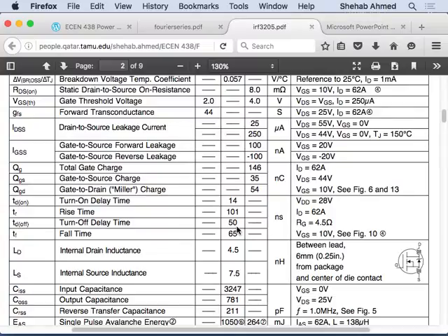We call it duty cycle. So the amount of time the device is on, you can call it the turn-on time or the duty cycle. In power electronics terms, it's called the turn-on duty cycle. The amount of time that the device is on. If I choose a device that's slow, I'm thinking I'm getting a certain amount of turn-on time while I'm not. What is that going to do? It's going to affect my average value. And what am I doing in power electronics? All I'm doing in power electronics is taking these waveforms, chopping them up, and then producing an average waveform out of that. So if I'm producing an average waveform that's wrong, then I'm not doing my job.